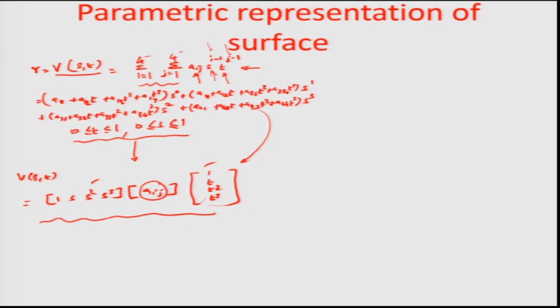In this particular case, it is a 3-dimensional surface that we are talking about. So, obviously, both the s and t would vary between 0 and 1, and so there is going to be a slope with respect to s and a slope with respect to t at all the 4 corners, because obviously, as a planar curve would hinge to 2 points, the beginning and the end points, a surface would hinge to 4 points, like a rectangular or square surface corresponding to S0 T0, S0 T1, S1 T1, and then again S1 T0. So, you will have 4 different end conditions this way, 4 slopes, and so slopes at these 4 points along both the directions, and there are cross slopes.